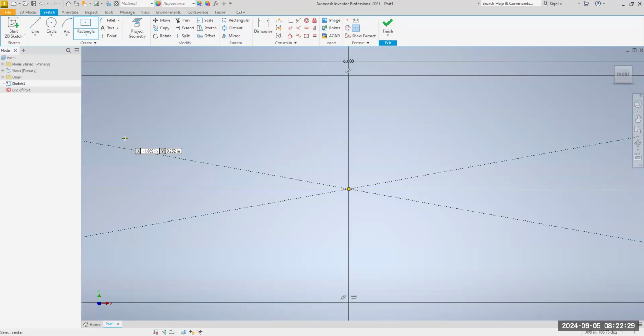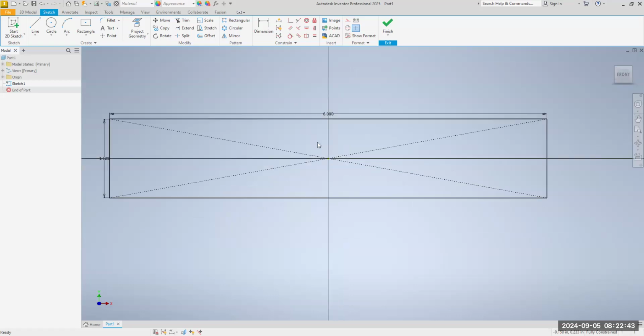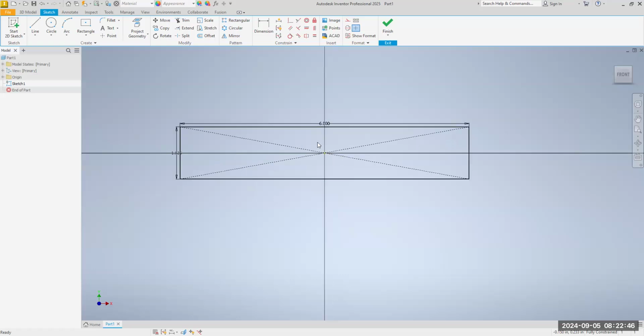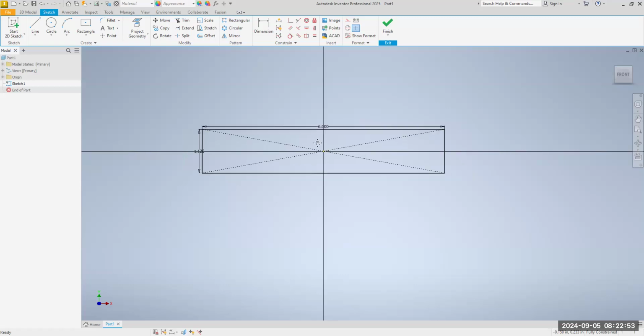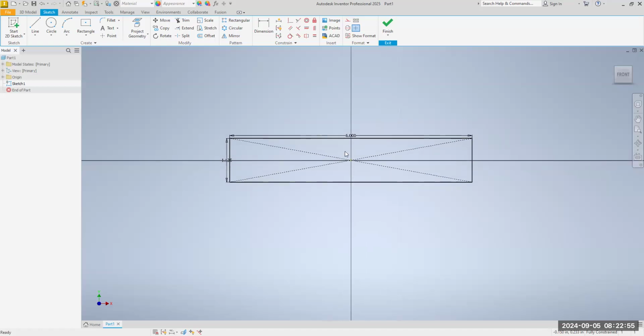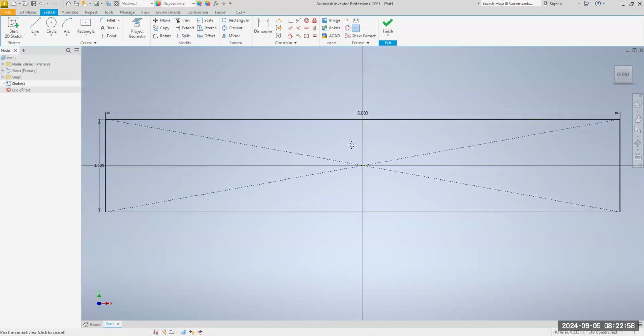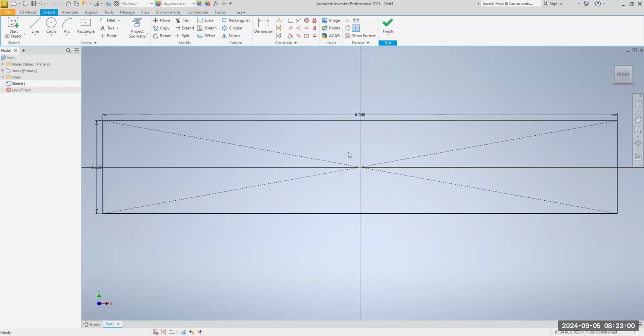Listen carefully now. Do a right click, select OK. Now you are out of that mode. Mr. Morris, I cannot see all the geometry. Take your scroll wheel and rotate it away from you. You should be able to see the entire rectangle now. Again, you can hold down the scroll wheel and pan as necessary. So you have control of your zoom. There's other ways to do this, okay?